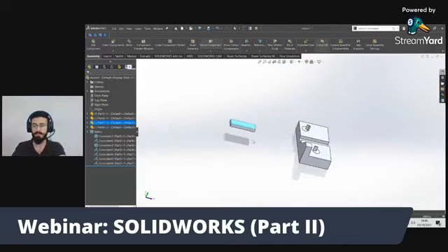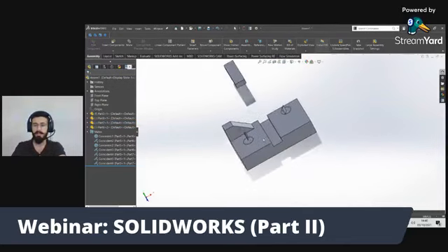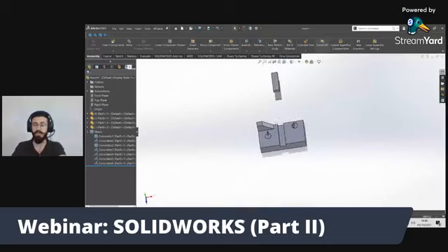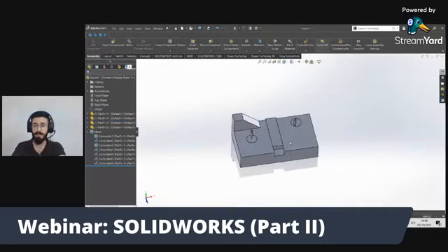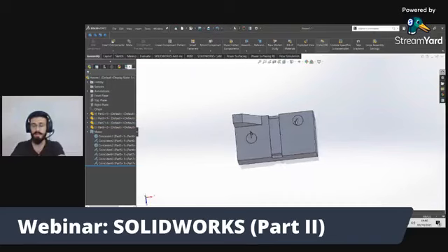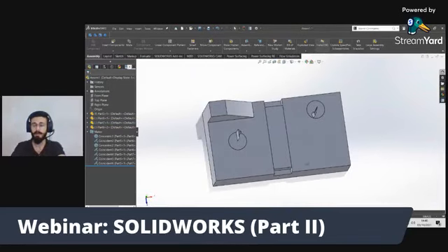I have to fix this, but I can't fix it like that. I could fix this back and forth movement between this face and this face by using parallel mates, but I can't. Why? I want to fix it here, but I can't place the concentric because the faces are not of similar length. I will be going to advanced mates.